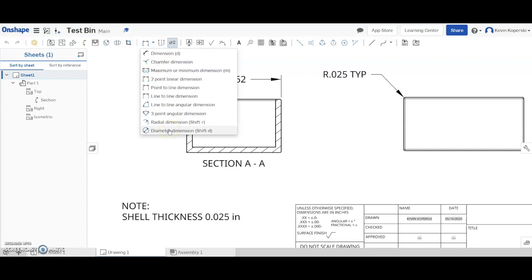If you're looking at a hole, you can be looking at the diameter dimension, remember, because you want the size of it, and then create a note similar like here and tell us how far down it goes. There also is the hole callout, which you can use. So again, it kind of depends on your preference and what design you have. If you have multiple things, guys, please use this week and ask us questions, but good luck and have fun.